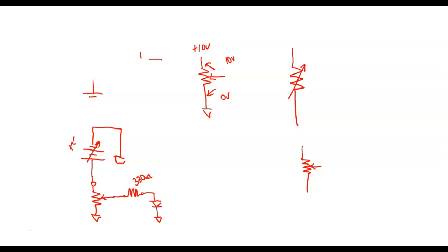If it was a ground, you could take an ohm meter, put it in that black one that says ground. You could unplug this thing. You could hook it up to the little ground terminal on there, and you'd measure 0 ohms. And Lee did that the other day, by the way.